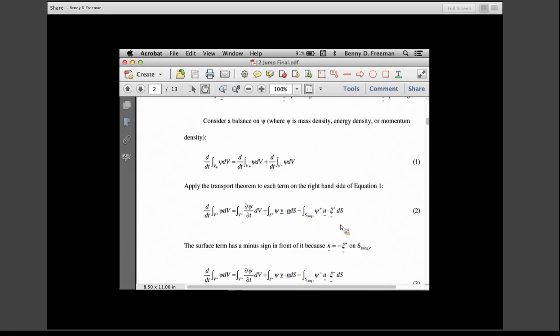One is the mass density integrated over the surface associated with V plus, which is S plus, and then there's also a term that is generated that is associated with the integral of the mass density on the plus side of that phase interface times the interfacial velocity.